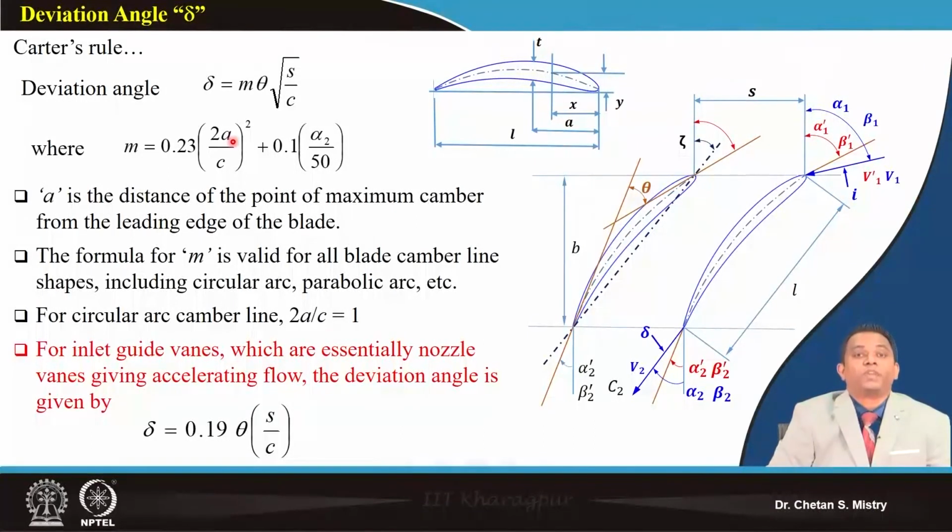Now, as we have discussed, we are moving towards very aggressive designs, meaning high pressure rise is expected from our blades. When we expect high pressure rise, my delta beta is bound to be high, and under that condition we need to do careful calculation for this deviation angle. Based on older available data from the cascade tunnel, people take this deviation angle as a first cut approximation.